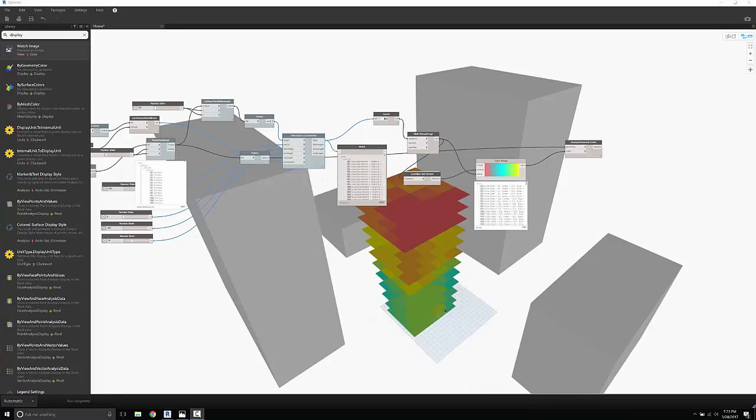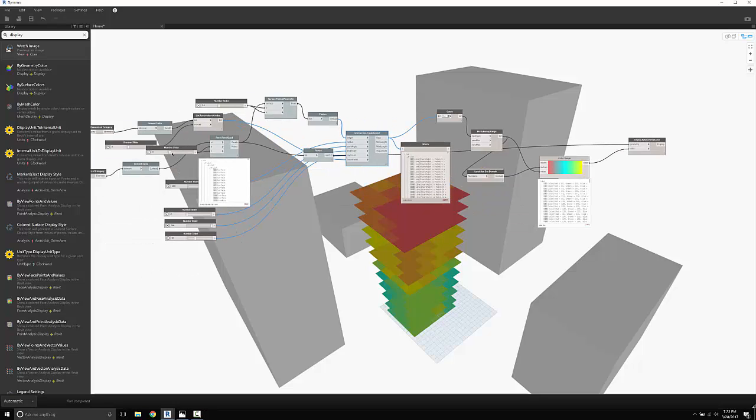And here you go, as promised, a much tighter gradient. I've turned the preview off on the actual Isovist. I've got 30 of them here. The other thing that of course you can do to get more accuracy would be to turn up, say, the divisions on the surface. Now, please be really careful here. So, for instance, when I go from 4 to 6, it's going to go from having 16 quads on each surface to having 36. So this is probably going to think quite a bit, and I'll pause again and come back to show you.